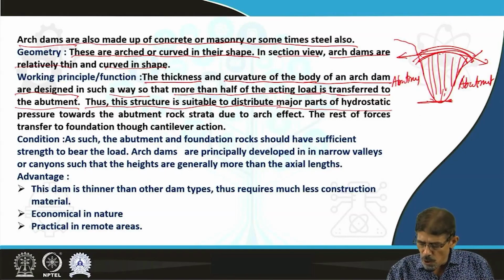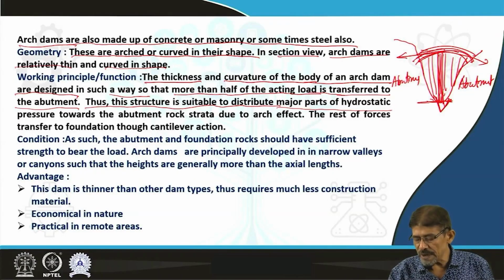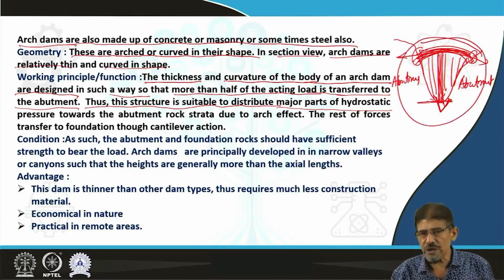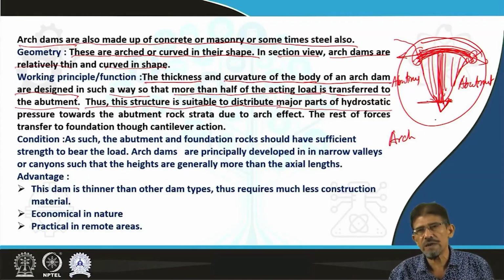If more than 50% of forces are transferred towards the foundation and less than 50% towards the abutment, then this type of arch structure is recognized as an arch gravity dam, because the major transfer of forces follows the principle of a gravity dam.